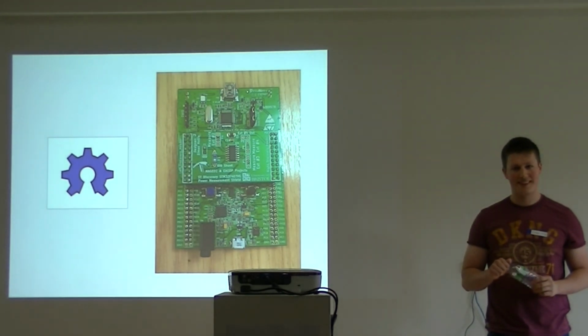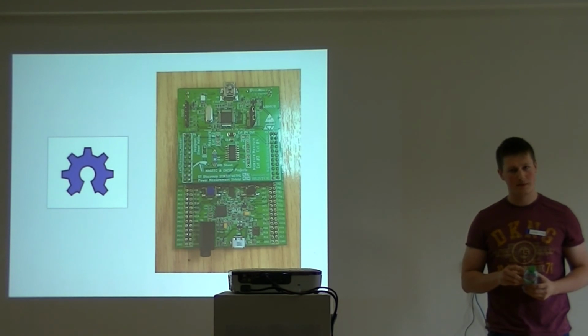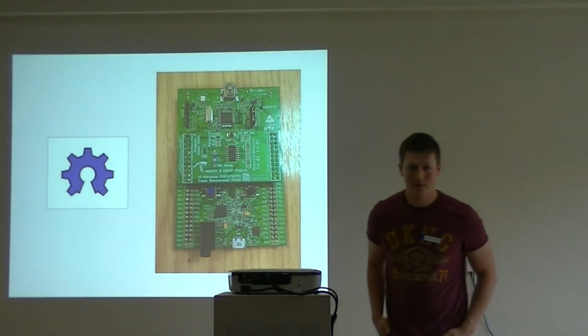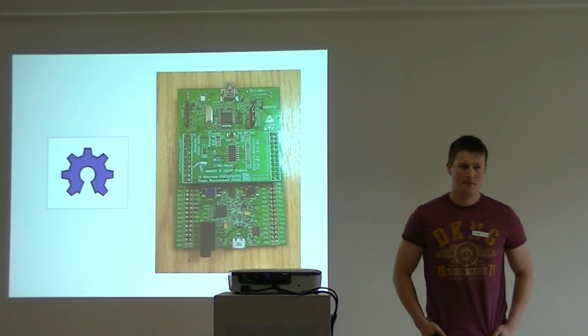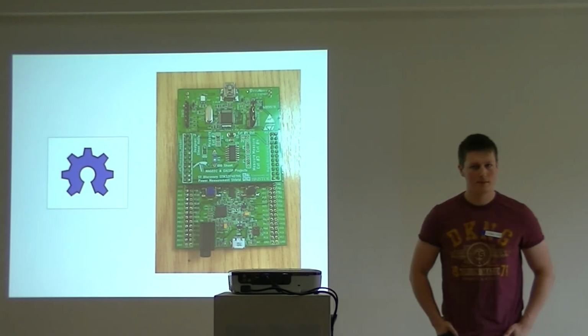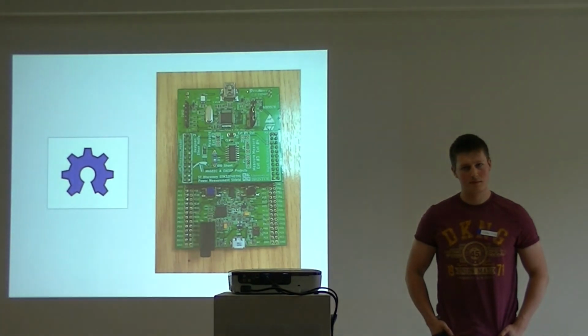There's some interesting research that James has done, which is what this was developed for, which is about measuring exactly that. The broad thing is, speed and energy are correlated. But you do find interesting things like on the high-end ARM processors, doing multiplication in the Neon coprocessor is actually more energy efficient. So you don't do it for speed, you do it for energy, which is why when you go up to high optimization levels in GCC, when you start getting the coprocessor pulled in, your energy consumption goes down because it's doing its multiplication in the vector coprocessor. And so there are some odd effects.